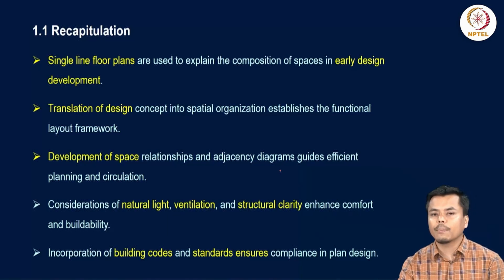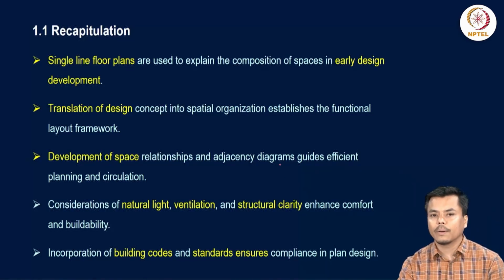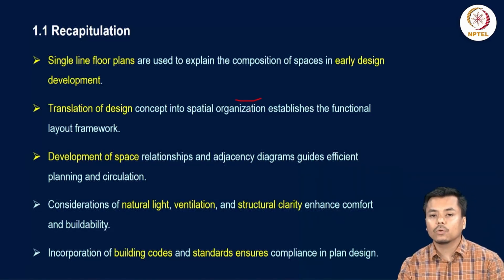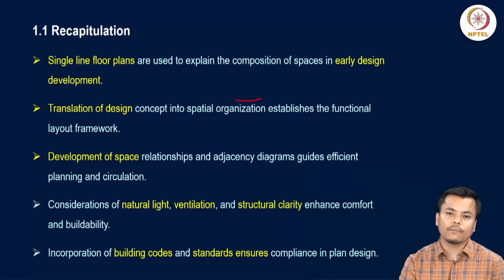So to give you a recap of what we had covered in the previous presentation, I presented you the details about single line floor plan. These single line floor plans are used to explain the composition of spaces in early design development. This translates the design concept into a spatial organization. This has to be understood in detail, because you cannot abruptly jump from a concept to the preparation of double line floor plan. So there has to be a transition step, that is the single line floor plan step.